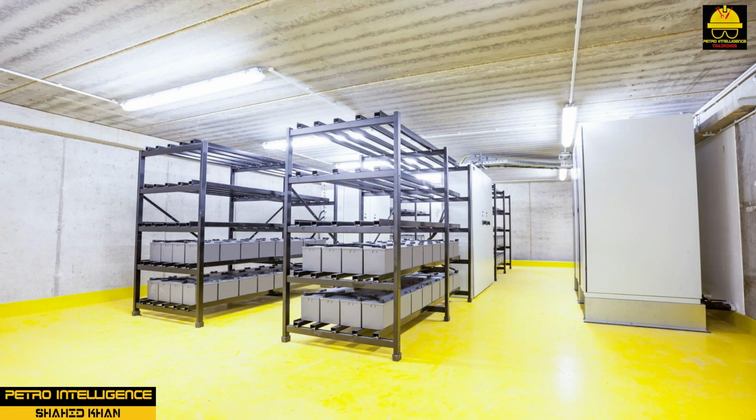The critical instrument systems are supplied with power through an uninterruptible power system, UPS. This system contains batteries, a battery charger, inverter, static transfer switch, and manual bypass switch. This backup system ensures that there will be no interruptions to alarms, computer control systems, and all other instrument systems. Many plants generate power in addition to that purchased. This is generally at a voltage level of the supplier or at the highest transformed plant voltage level.